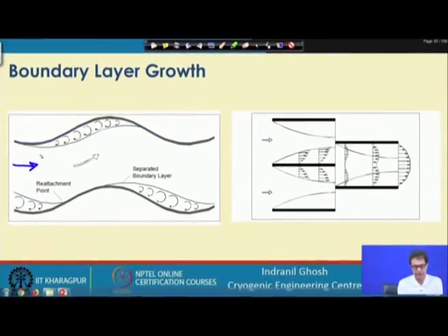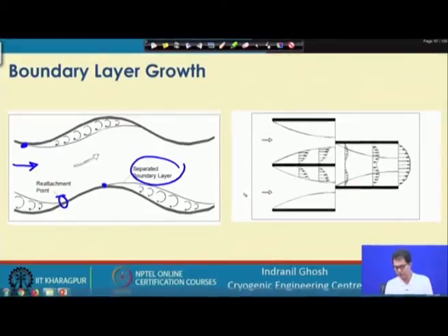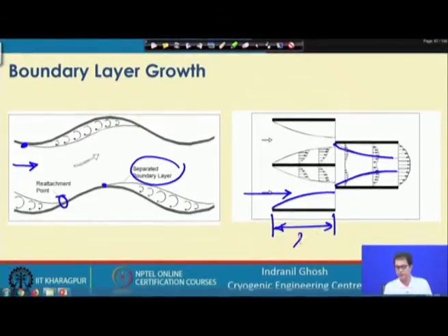So, when the flow is taking place, we will find that the boundary layer is getting separated at this point or at this point, and there are breaks in this region, and again it will join at the reattachment point at this layer. And in the case of the offset strip fin, the flow is getting developed up to this part, and there is a fresh generation of the boundary layer at this point and this point. So, at every regular interval, as I told you, this is the lance length called L, we have a generation or breakage of this boundary layer, and as a result this boundary layer is regularly getting interrupted at these locations, resulting in enhancement in the heat transfer at the cost of some pressure drop penalty.